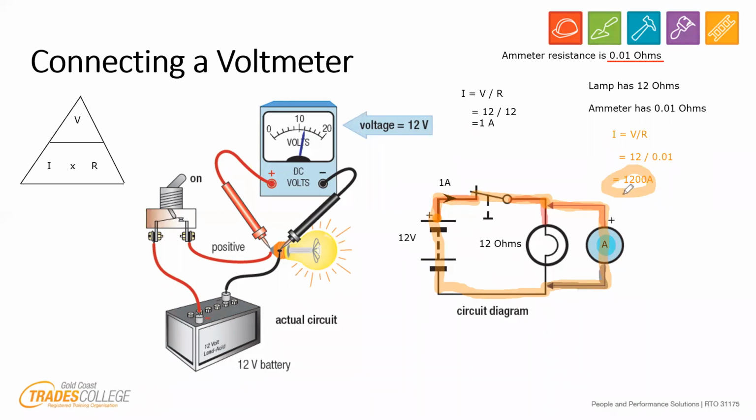So current, guys, is heat, same thing in DC circuits. So that's going to create a lot of heat, and there's a serious danger there. Because you've connected that in, best case scenario, you've got to buy a new tester. Worst case scenario is the tester could be damaged, it could have blown up in your face, could have burnt you, who knows. So something as simple as choosing the wrong setting on a multimeter can cause serious issues like that.